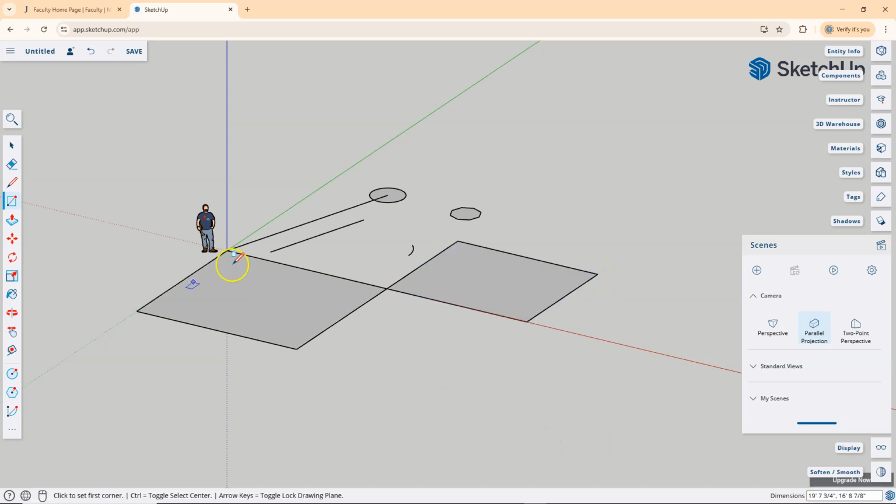You'll notice that anytime you edit a closed boundary, it's going to bring that surface back. Okay, but at this point, now I can use this next tool. It's called the push-pull tool. This is one we use quite often. And this is basically going to turn a 2-dimensional object, like a rectangle, any enclosed boundary, into a 3-dimensional object.